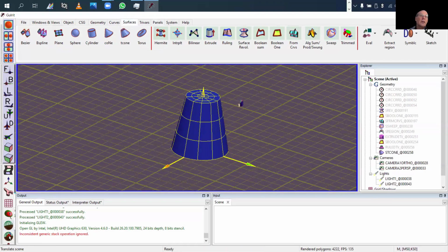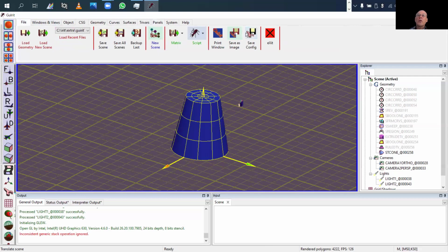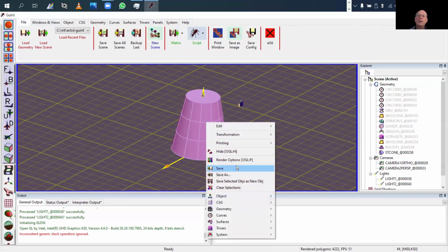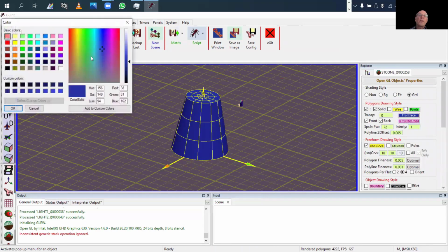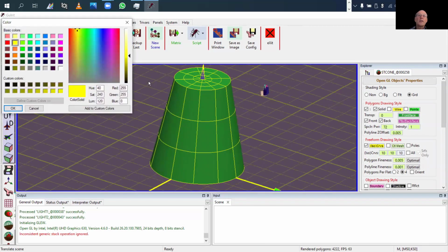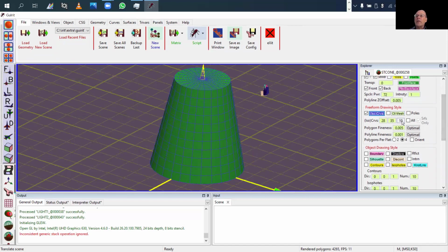So again, this here and the same thing in the panel is the default behavior, and you can save the configuration and it will store that. However, you can also override that clearly. If you right click here or right click there, there is a rendering options entry here also. And if you do this, you can change the color, say green. But you can change many other things. You can change, for example, isocurves to be blue. And you can change the number of isocurves in one axis and in the other. And in fact, if it's volumetric, you also have a third direction.